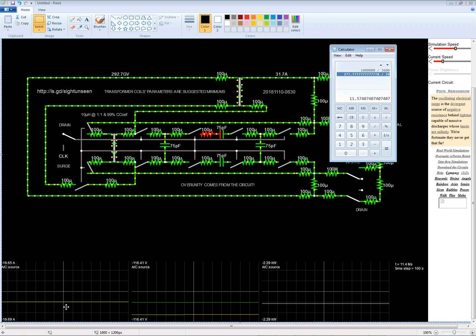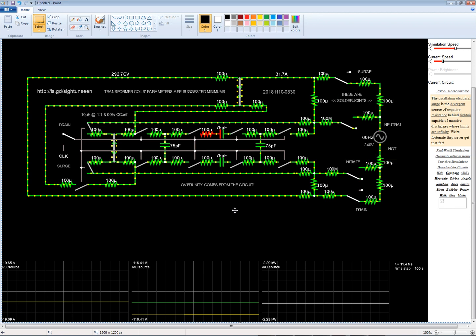But it's DC. You're not going to be able to run anything off of this unless it's light bulbs, because it's DC, it's not AC. Non-motor loads, anything that does not involve a motor. Your refrigerator involves a compressor motor, so you're not going to be able to run your refrigerator. So that's why I chose to keep to hopefully under 15 amps, but I didn't change this 240 volts. I should change this to 120.